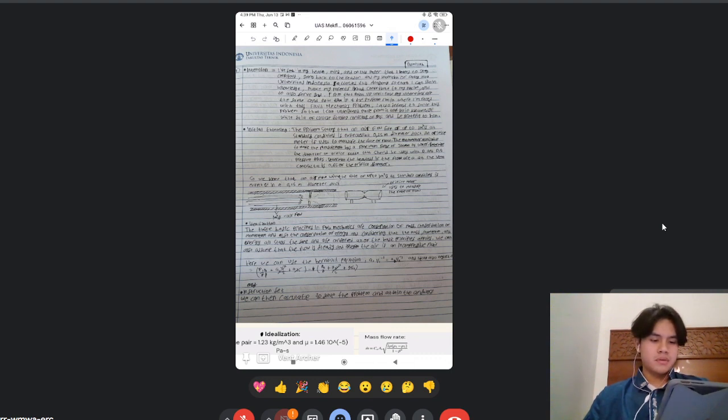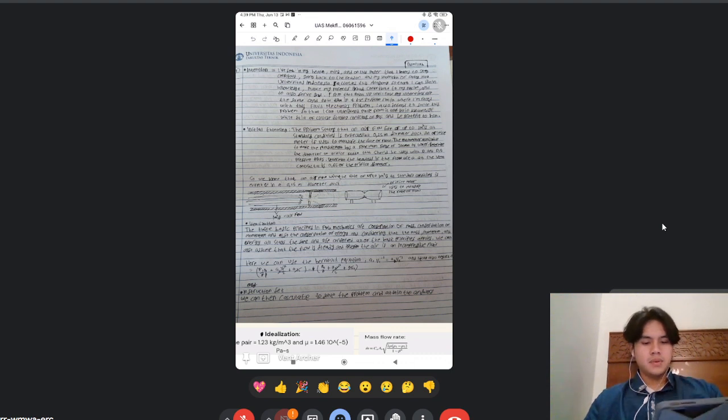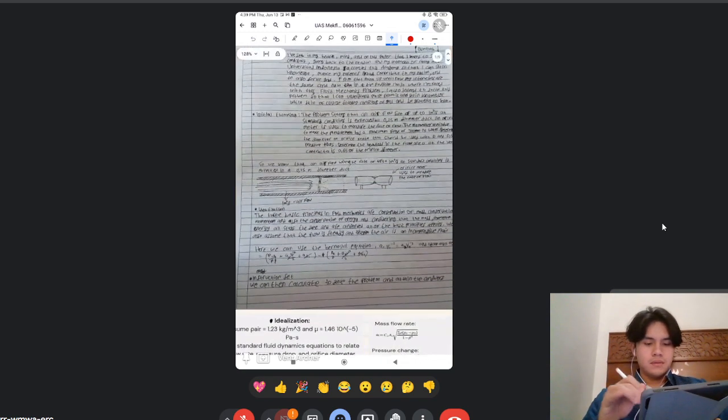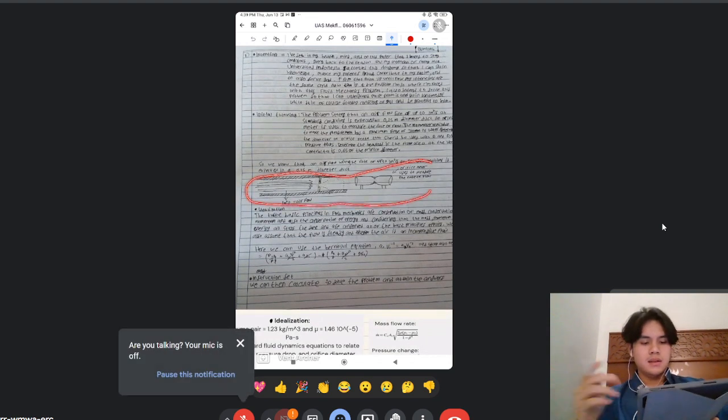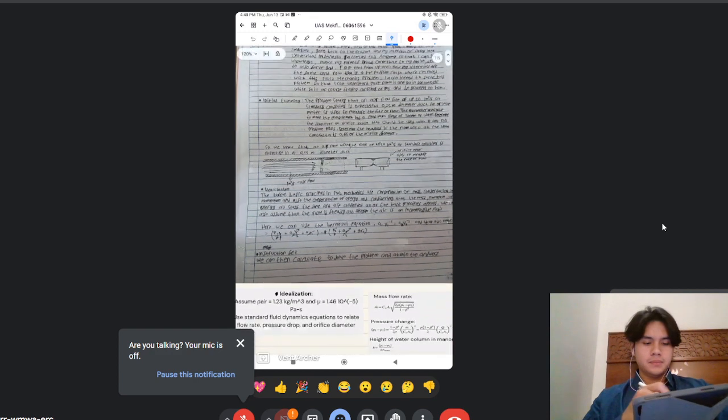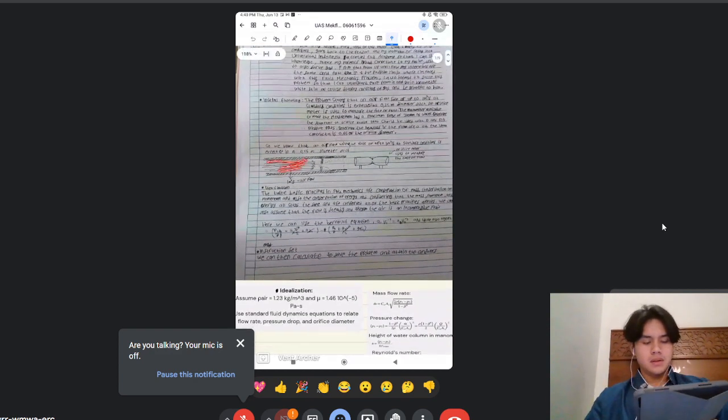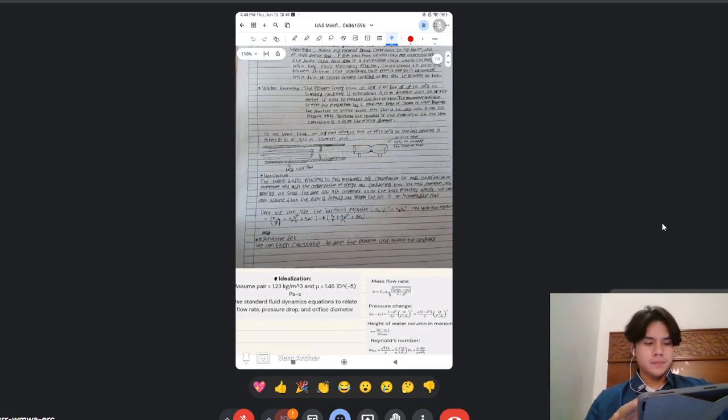Determine the diameter of the orifice plate that should be used with D and D/2 pressure taps. Determine the head loss if the flow area at the vena contracta is 0.65 of the orifice diameter. Here I've visualized the orifice and the duct itself, the airflow of 1 meter cube per second. There's the orifice, and we're going to measure the rate of flow.